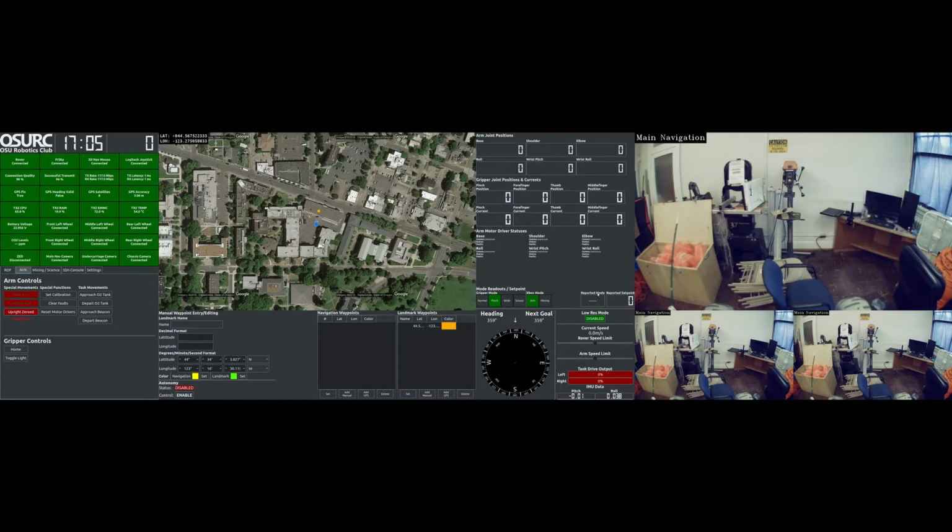Down here you have the reported mode and set point. These come back from the gripper. It was again another sanity check thing while we were doing debugging. It shows us what mode the gripper thinks it's in. Right now the software is actually limiting it to pinch only, but this tells us what the gripper thinks it's in, and then a reported set point, which is the value I send it from 0 to 65,535. It's what the gripper says, hey, I have this number, and is sending back. Again, mainly just used for debugging.